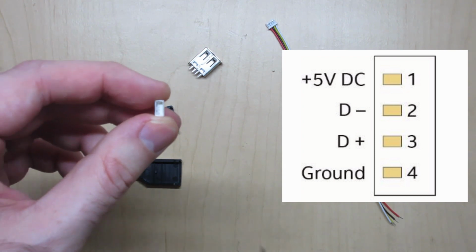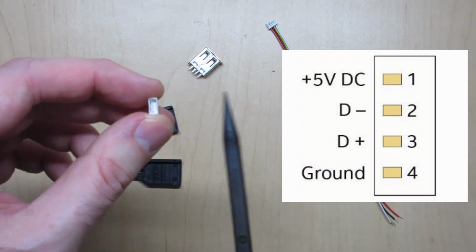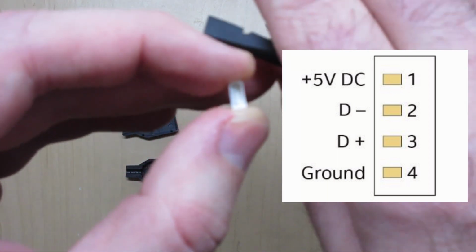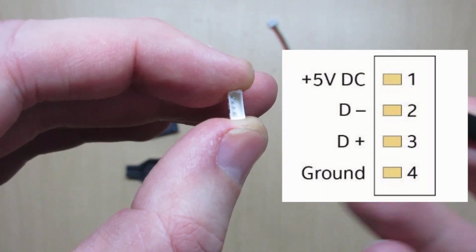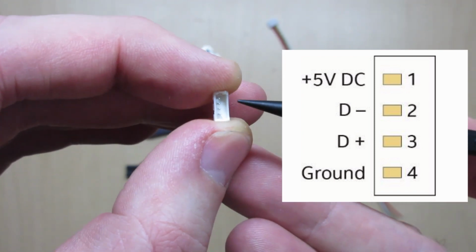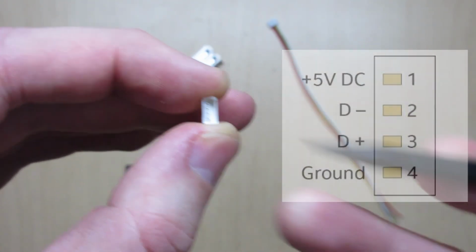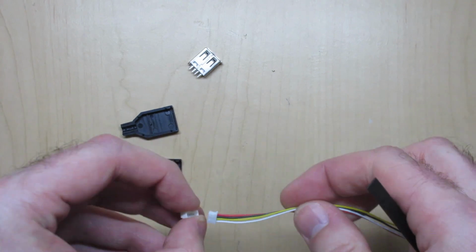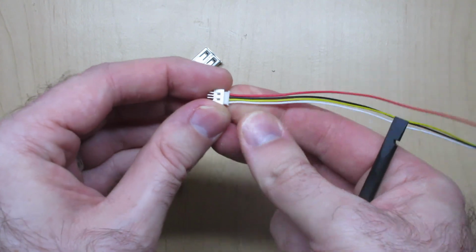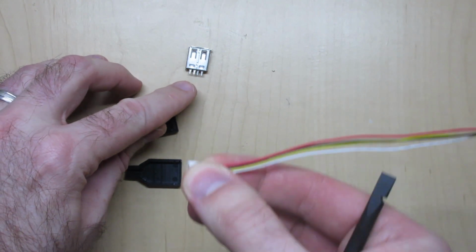So then we go over to the male side of the PicoBlade connector. And Intel has done a nice job and shown us that the pins are on the left side in their diagram. So they're recessed as far as they can go inside the terminal. And if we look at this, I'll try to get this into focus, then that's going to be pin 1, pin 2, pin 3, pin 4, top to bottom, which of course translates to V plus, D minus, D plus, and ground. So all we've got to do now is try to fit this cable into this slot, and it will fit somewhere like that. And therefore now we know the colors that we need to map to the terminals on the end of the USB connector.